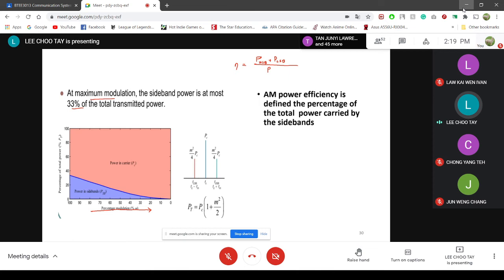At the same time, I take the message signal and perform a phase shifting process so that I can get the other version of my message signal, which is the original one phase shifted by 90 degrees. I multiply it with the same shifted version of my carrier signal.